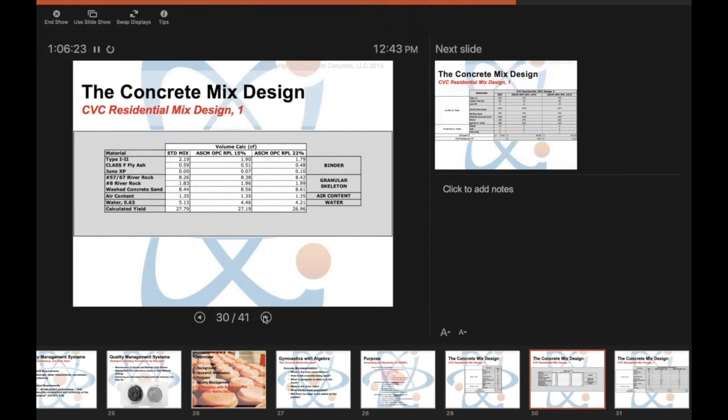Now, we can reduce the cementitious significantly, but the problem is at a certain point, if we don't have a good aggregate to paste ratio, we start going from creamy to dreamy to bony and nasty. So what I'm doing here is making up that volume with my coarse and fine aggregate.